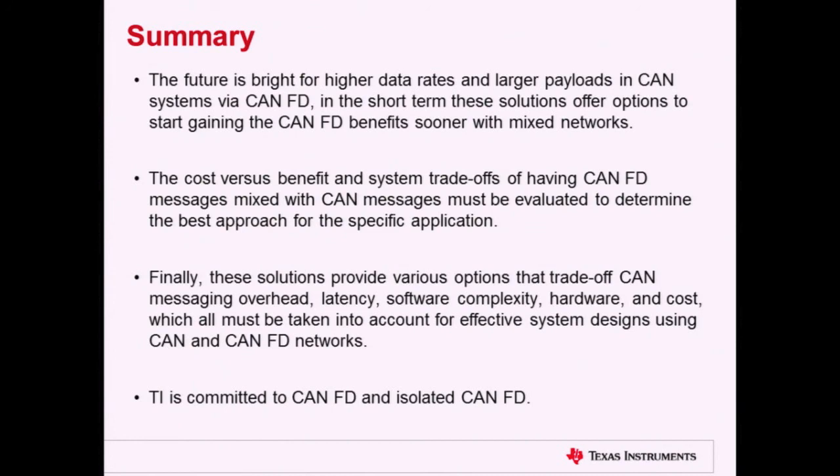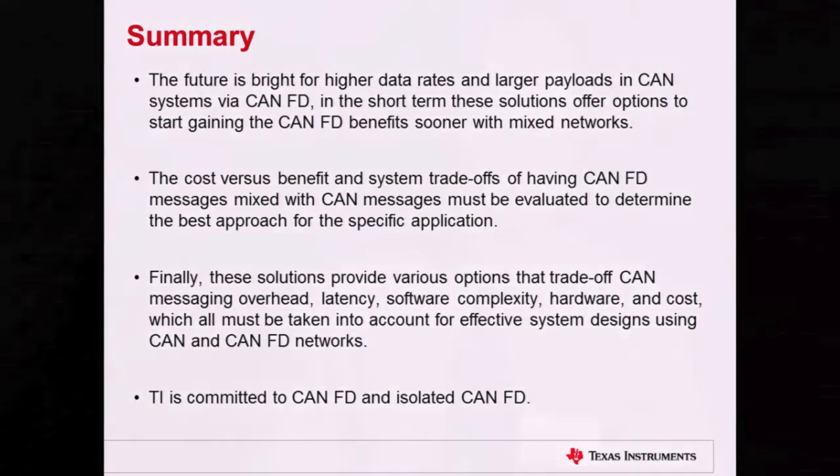The cost versus benefit and system trade-offs of having CAN FD messages mixed with CAN messages need to be evaluated to determine the best approach for a specific application. And finally, these solutions give various options to balance the overhead, the latency, the software complexity, hardware and cost, which all need to be accounted for in the specific application that you're trying to achieve.